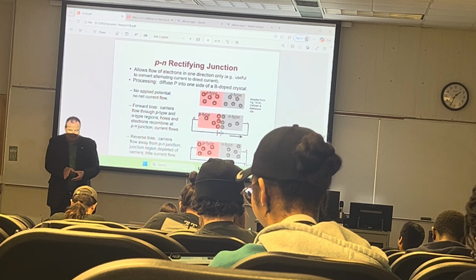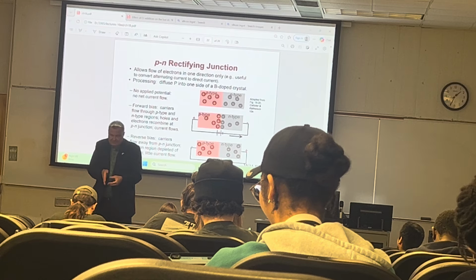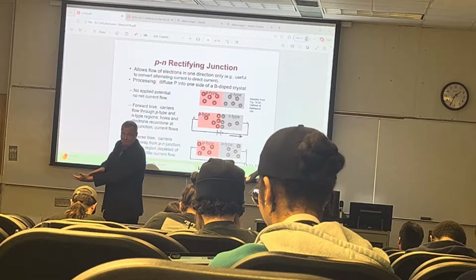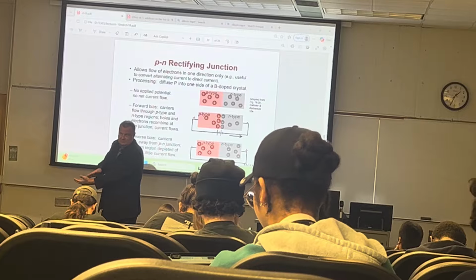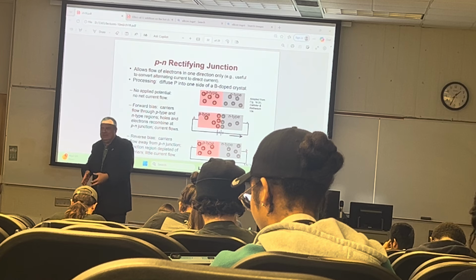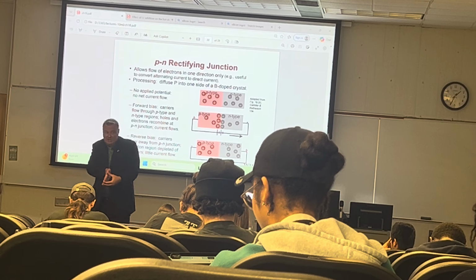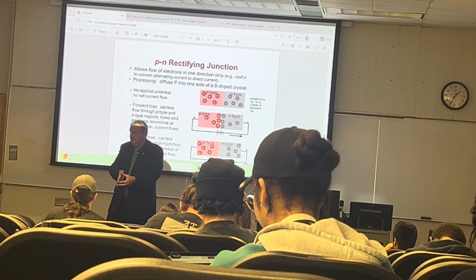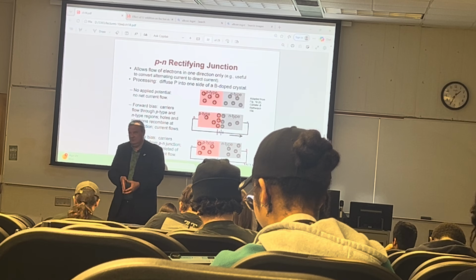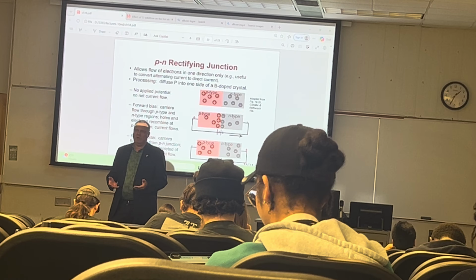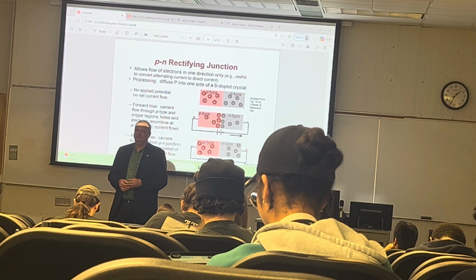If the fluid is flowing in this direction, it's pushing the flapper and the fluid goes through. But if for whatever reason the pressure is higher on this side and the water is trying to go this way, the flapper locks the pipe and the water doesn't flow. Why would you need a flapper valve? Ever?